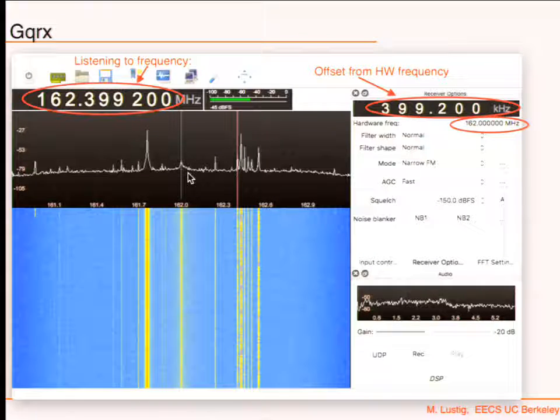Like when you compute an FFT or a DTFT, then you've got the zero frequency and you have the higher frequencies, the Nyquist frequency, and you span basically minus pi to pi. And these frequencies represent minus pi to pi. They also represent, in this particular case, 161 megahertz to 163 megahertz. But it's really minus pi to pi in discrete frequencies. They have correspondence to the analog ones, but once they're samples, they're minus pi to pi. So you stare at this spectrum.